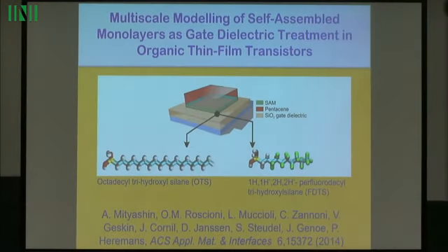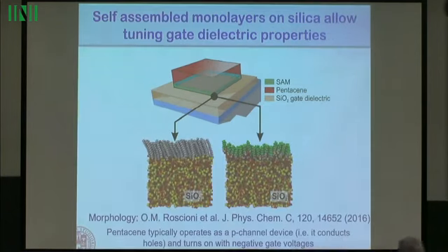And then with soft, we've studied this in collaboration with people doing real organic devices, people at IMEC in Belgium, who actually make real things. It's very difficult to tune the surface of an insulator or electrode, but in this case an insulator. One of the ways they do it is to cover the surface with long chains. So we studied silica, the insulator, with an added self-assembled monolayer, either alkylated or fluorinated. Notice that the alkylated ones are tilted with respect to the surface, and this is true in reality. The fluorinated instead stand up. And on top, pentacene, which is a classical semiconductor.